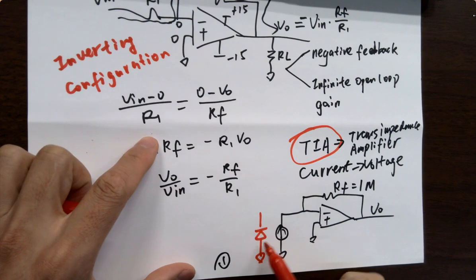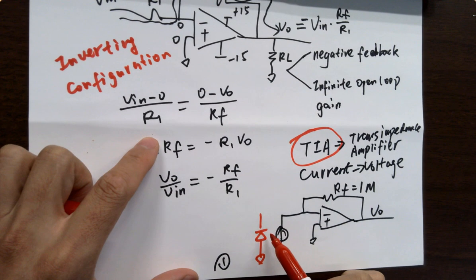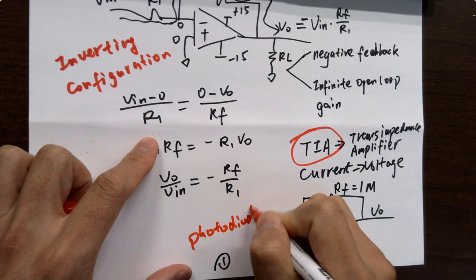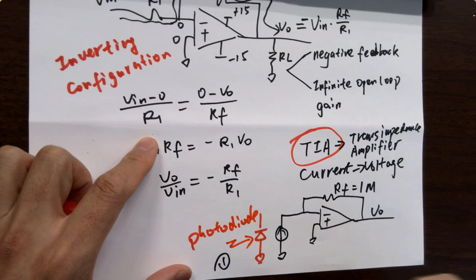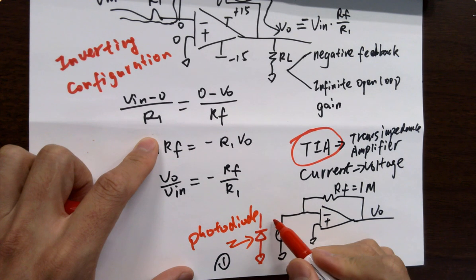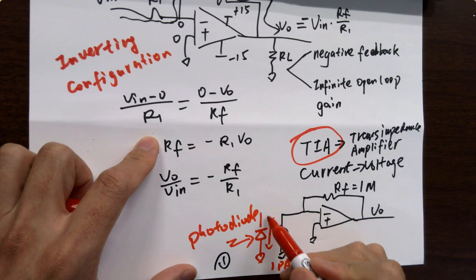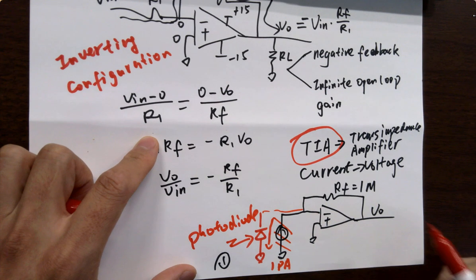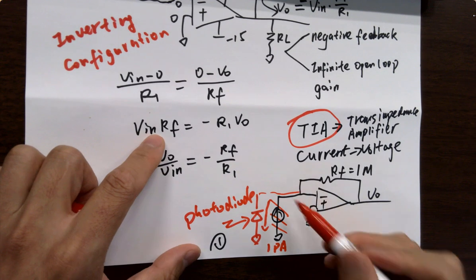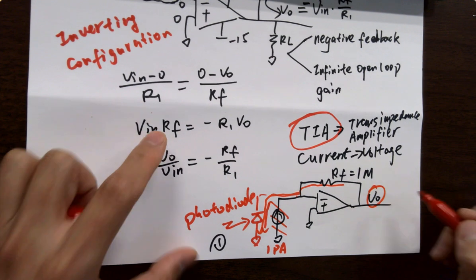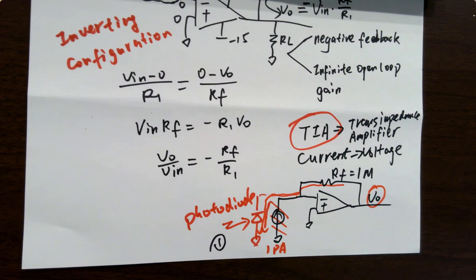If you use this little diode as a photodiode, it will be able to intake photons and convert into a photocurrent. It's tiny, usually in picoamps, for example, 1 picoamp, to replace this current source as a model. So this current is going to flow through here to ground and create a voltage, which is called VL. So that's how you get the voltage signal of the cameras.